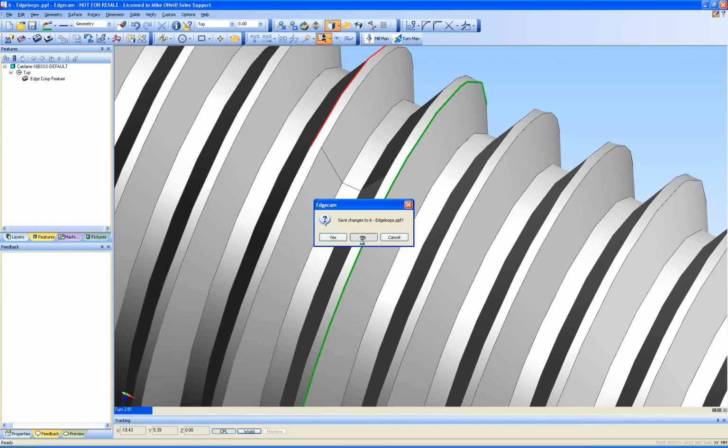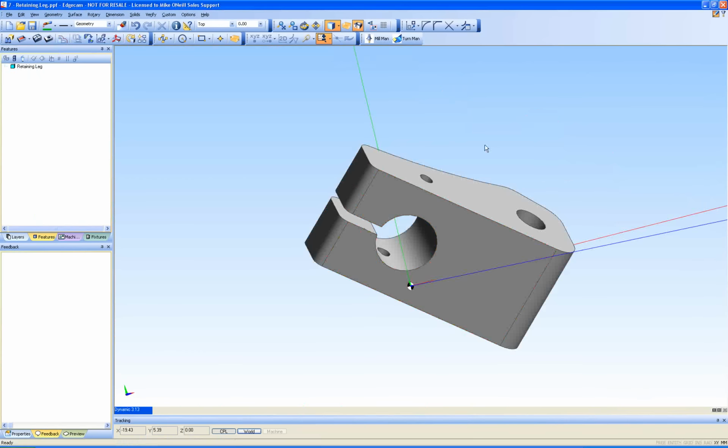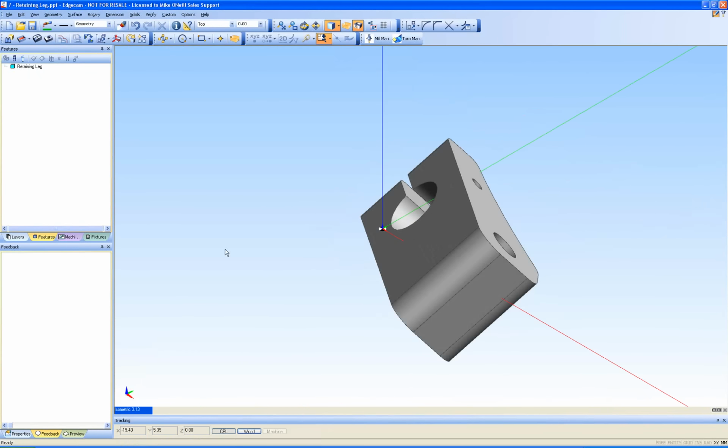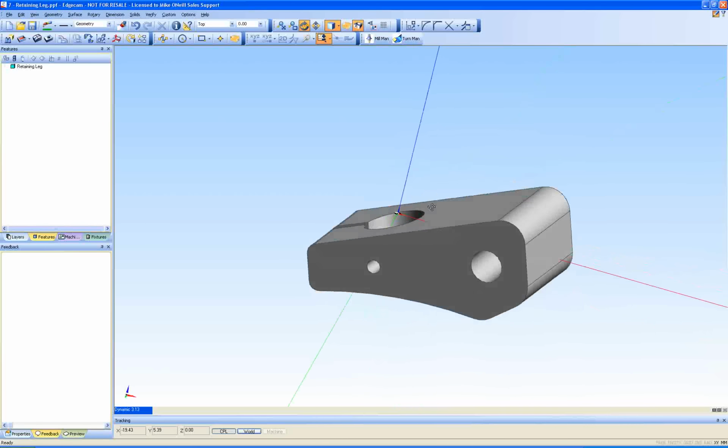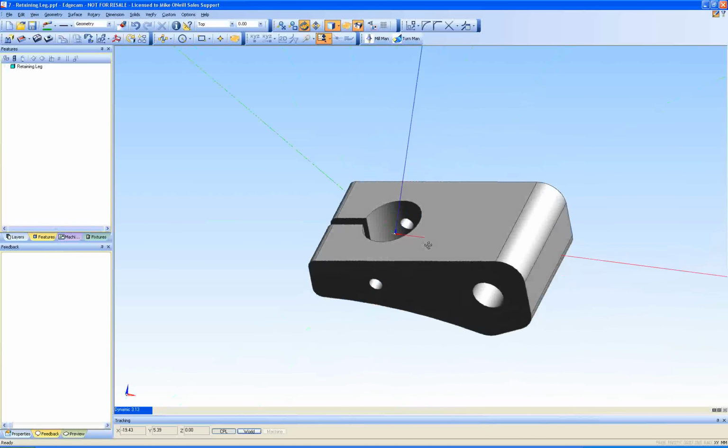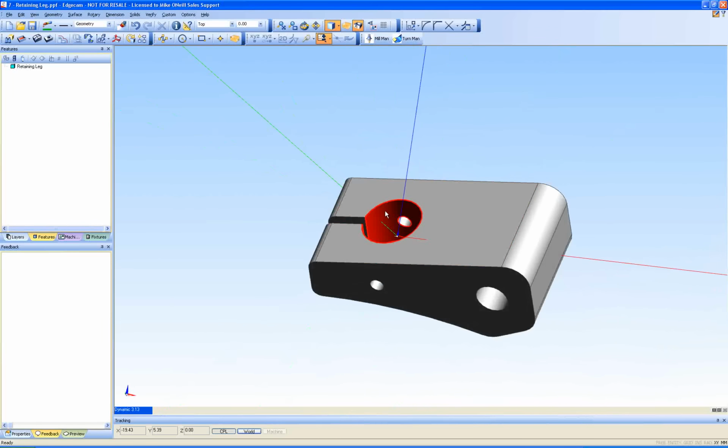Another item that I'd like to demonstrate to you is align body, the align body command that we have in milling and also in turning. In this particular case I've exaggerated the CPL marker, and what I wish to do is to feature find this hole. I assume that this face is perpendicular to this hole, and obviously we'll find that that's not the case. But let's continue.